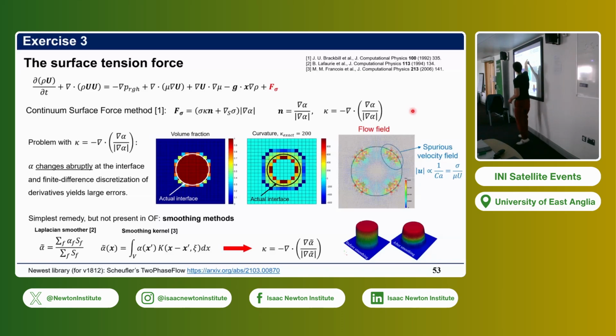Imagine that you're feeding your momentum equation with many mistakes, so you're imposing an external force on the flow at the interface. If you don't do things right, these spurious velocity fields may kill your simulation. They may not be a problem if the Weber number of the flow is very large, so surface tension doesn't play a big role; you may get away with it.